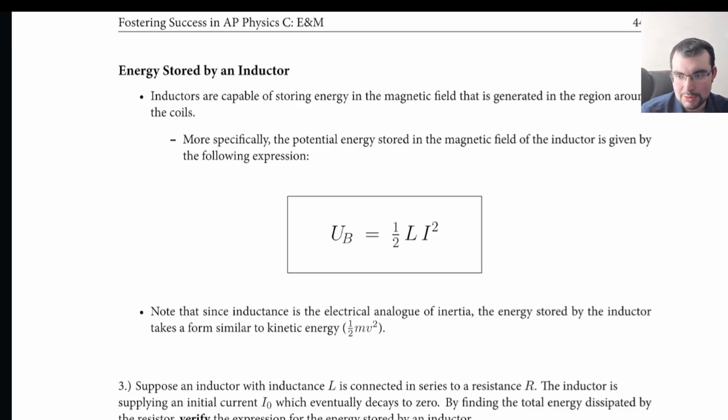So it actually helps to think about inductors or inductance as inertia. So inductance is this electrical inertia opposing change. If I apply a force on a refrigerator, it's not just going to instantly accelerate and start speeding up at a really, really quick rate. As I push on it, it's going to speed up slowly because that fridge has inertia. So yes, it'll accelerate, but is it going to reach its top speed instantly?